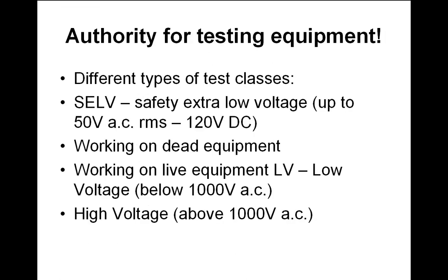Authority for testing equipment. There are different types of test classes, and it's just to go through this a little bit. I've got lots of health and safety sheets, and you just need to know about this. Just store it away in the back of your mind. There's so-called SELV, and that stands for Safety Extra Low Voltage, and that goes up to 50 volts AC RMS and 120 volts DC.